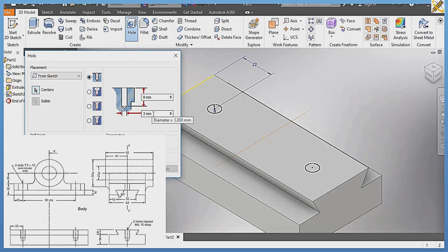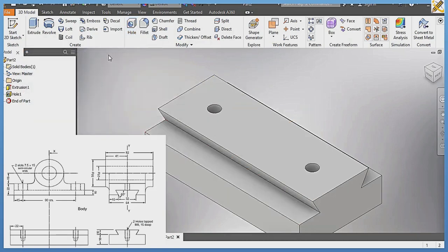So this area is to change the diameter. Diameter of our hole is 8. Let me pick hole 1 and hole 2, diameter 8, and the depth is 15, depth of 15. All right, so that's it. I'm going to press okay. So it is also settled.